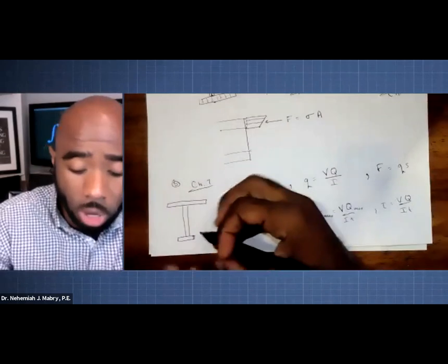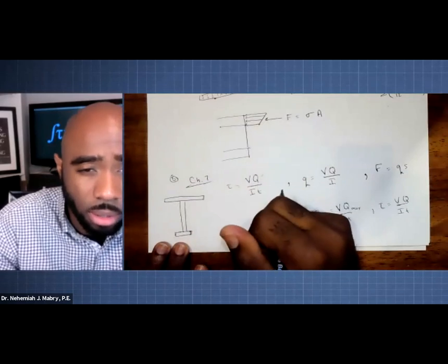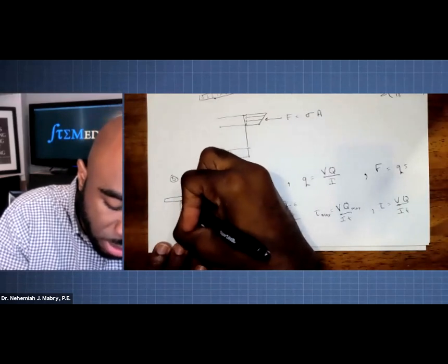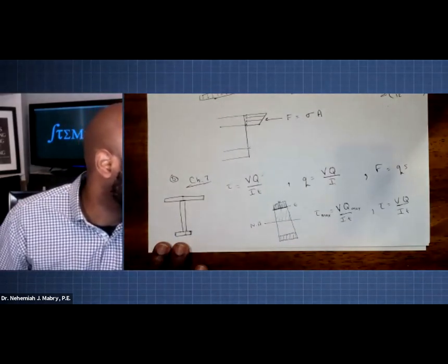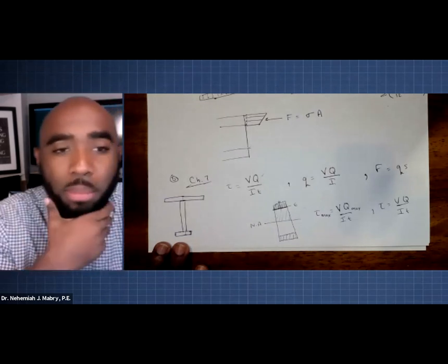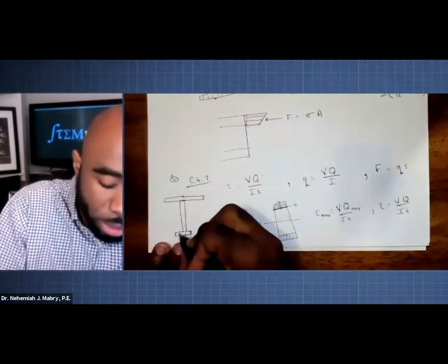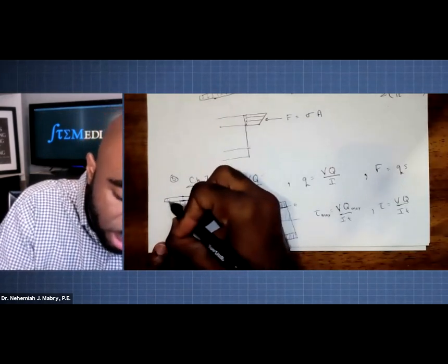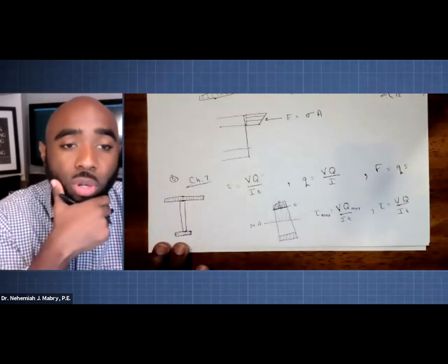Yes. So you're saying, if you want to know the maximum for here or here. If the point of interest is here, if you have fasteners here, let me think of how the question could be asked. It could be asked something like, what's the maximum allowable spacing? Because you have spacing here and spacing here at different nails, and they're going to be experiencing two different shear flows. So in this case, you're going to have to do both of them and see which one gives you the controlling one.